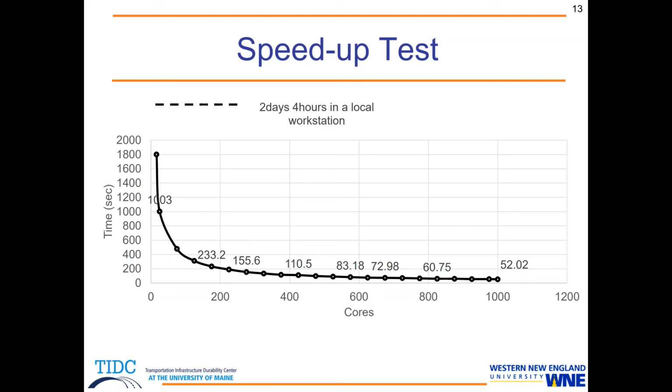But one more thing I wanted to point out about this in-house code is that it is able to change the number of cores with a fixed number of partitions. What that means is, with many other software packages, when you would like to use 1,000 cores, you have to partition 1,000 times, so partition numbers and the number of cores have to be synchronized.